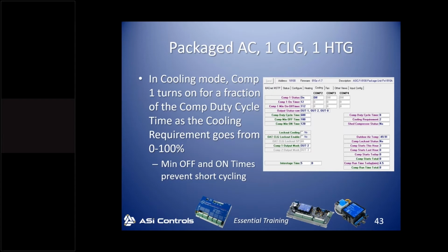So that means once it turns on, even if we had a 10% cooling requirement, the calculation would say turn on for 60 out of 600 seconds. But since the minimum on time is 120 seconds, it would actually run for 120 seconds before it was allowed to turn off. Likewise, once it turns off, it's going to stay off for 180 seconds at a minimum, even if the timing calculations were to say turn on more quickly than 180 seconds after you last turned off.